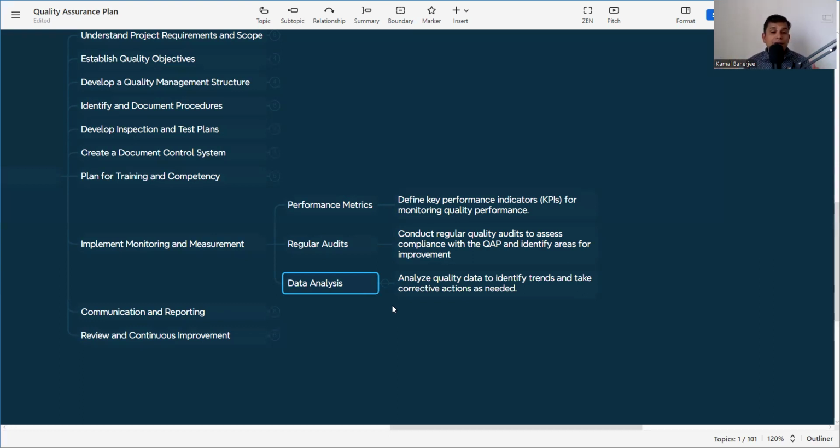That is the requirement we are not fulfilling. That is why it gets rejected. Now we need to analyze that data, why this is happening. Maybe it's the undulation. So why is undulation happening? Maybe a workman issue, so we need to define the training program for the workers so that they can do the work properly. Or there is cracking. There is a material issue. We need to test the material so that we can find out, and there will be no defect. So that is why data analysis is more important for the quality management system.